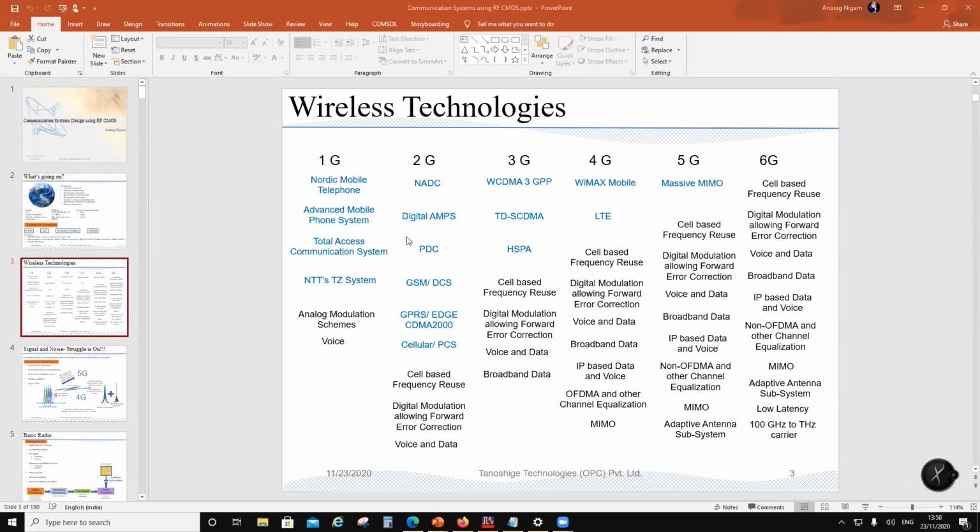Okay, so there are multiple access schemes. Like for example, how I adjust many subscribers in one system bandwidth. Okay, so there are 2 things which you should know. One is the system bandwidth, other is the channel bandwidth, right? So I might use different frequency for transmitting and receiving. Okay, so that will be frequency division multiple access.